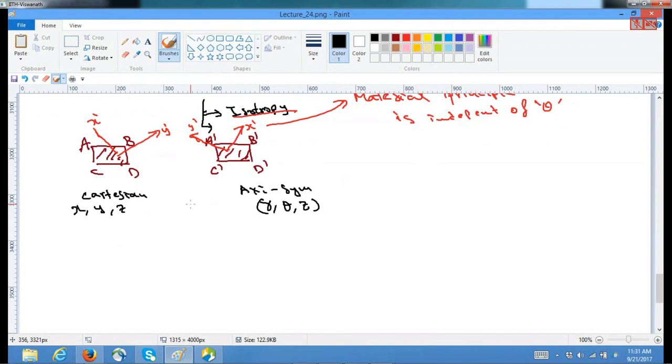hence our equilibrium equation, even though it is the same, has to be rewritten in terms of r theta z. So the same as your strain displacement relationship, even though the equilibrium equation remains the same, the terms in it would change. So it is like telling the same thing in two different languages, but the net thing what you're solving is the same.